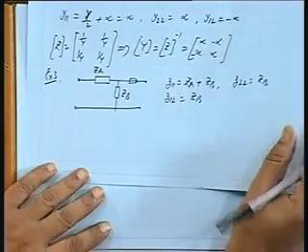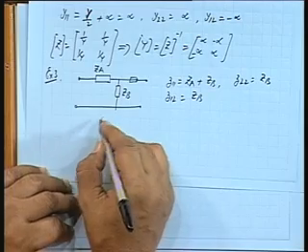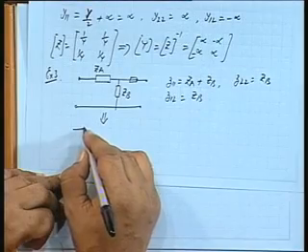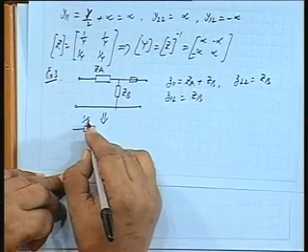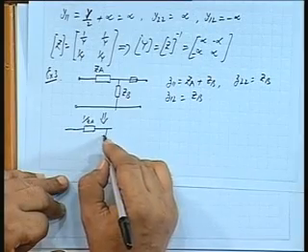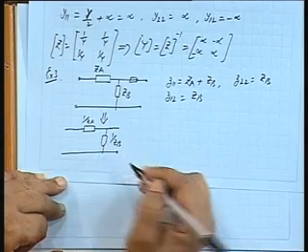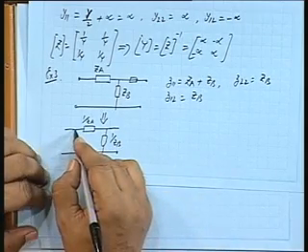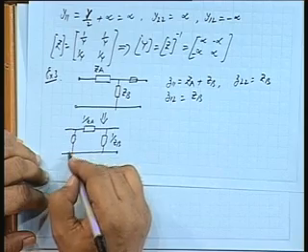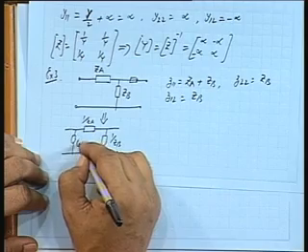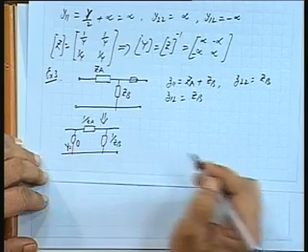Okay. Now, if you are asked to calculate the Y parameters for this, then I will take an equivalent pi. So this is 1 by ZA admittance, this admittance is 1 by ZB, and what about this admittance? Infinite impedance, that means admittance is 0. Okay.